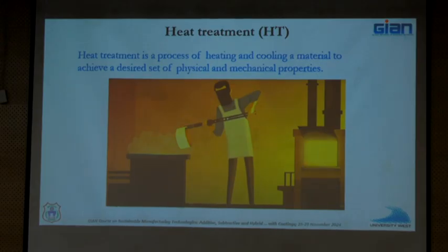So we are asking ourselves the exact opposite question, right? That if you know that you have to HIP because your airworthiness certification demands hipping, then what can you do, right? So everything that I showed you so far is assuming that you cannot do without hipping, and then what happens if you do it at 1120 degrees, 1185 degrees, if you do it on a good build, bad build. But for that, the answer to the question, do I need to HIP, should be clear at the beginning, right?